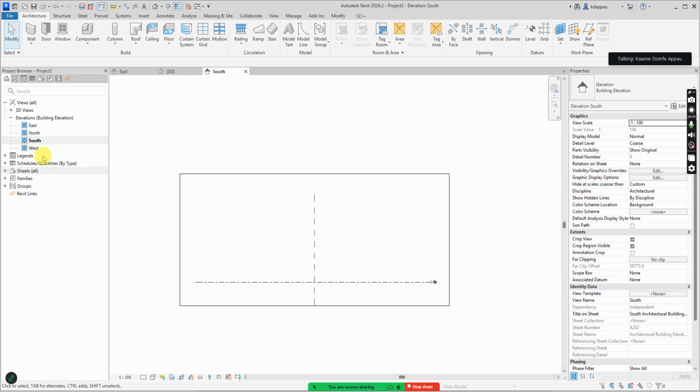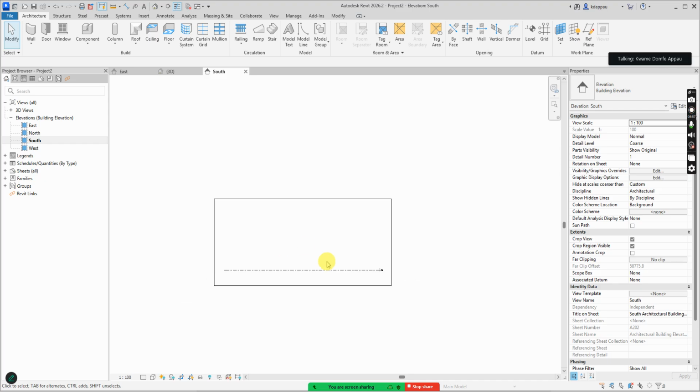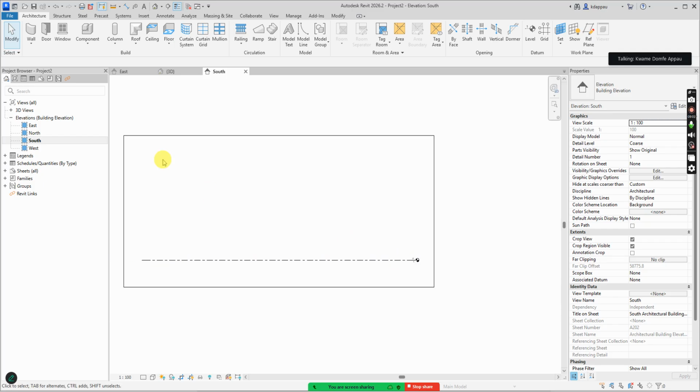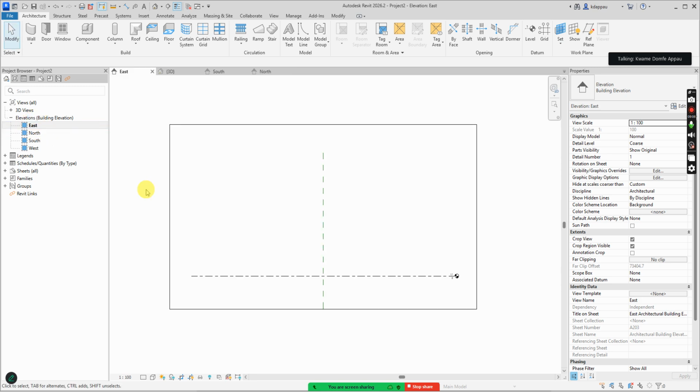I said it's okay. Delete everything from the view and leave only four elevation views there. Now, anything else, delete anything else you see on any screen. So you only see one level in any of the elevation views. Anything else is insignificant.